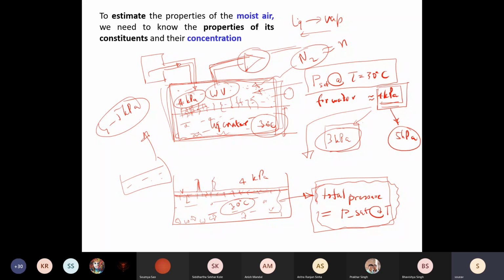But you will not see vapor starting from the bottom of this liquid column and traveling upwards. Because for this vapor bubble to be generated over here, at this location, unless and until the pressure inside this vapor is equal to the pressure exerted on top of it, it will not be able to escape up.